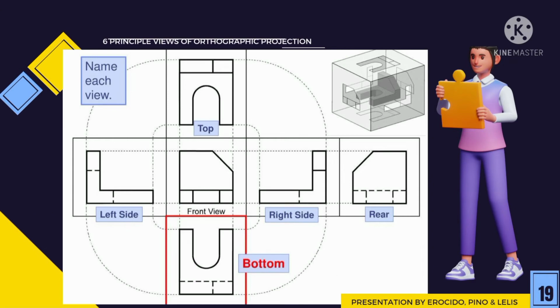If both sides of the object are symmetrical, it means that you don't need to separate them into a right and left side view. Next, if the front and back views of the object are the same, there is no point in drawing the same view twice. It's not exactly the same view, but the drawing would be the same. And the bottom view doesn't matter for the product if it is equal to the top of the object, either on a product or on a final drawing.